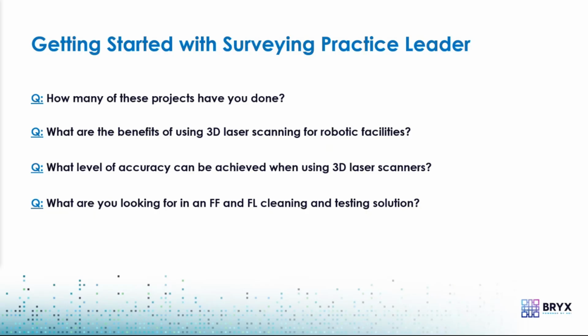Great question. So number one, on the cleaning side, because there are a lot of other contractors on the floor when we're out there scanning, we will capture their hoses and things like that, gear laid down on the ground, and things that'll get within the scan that need to be cleaned out. There are a lot of tools that come with your typical scanner software to help you clean that data.